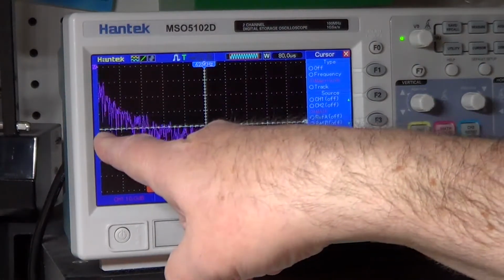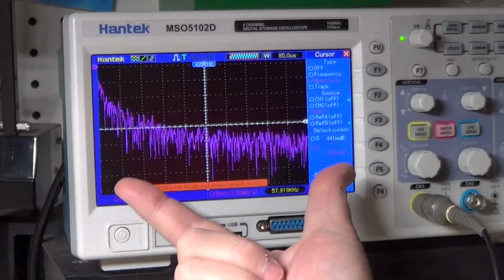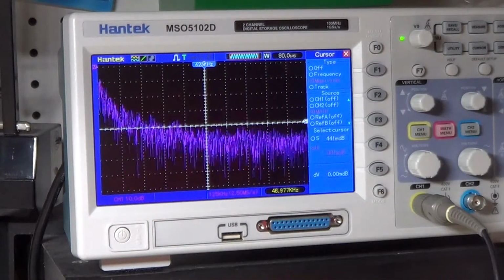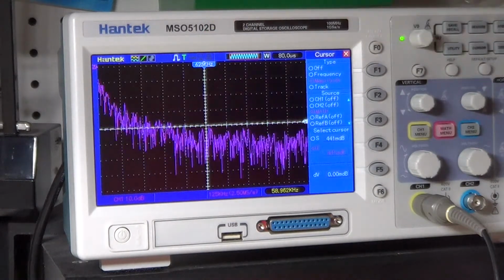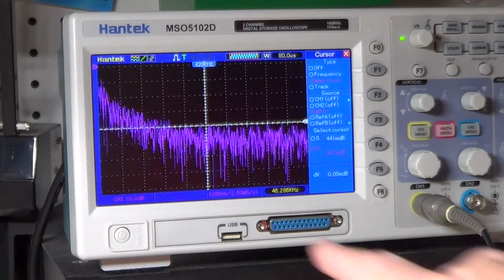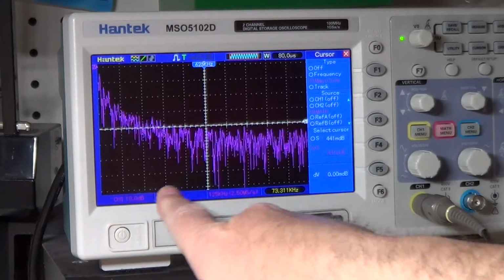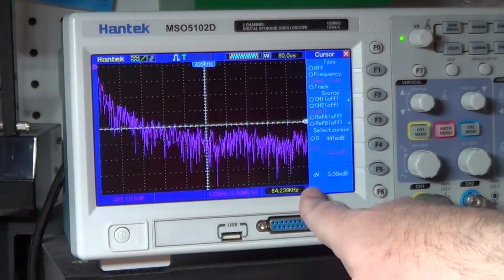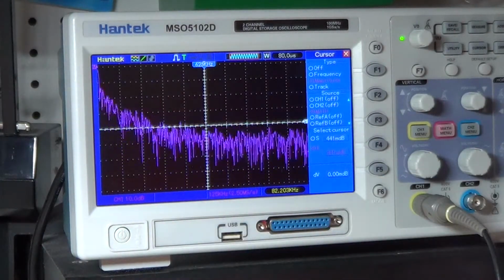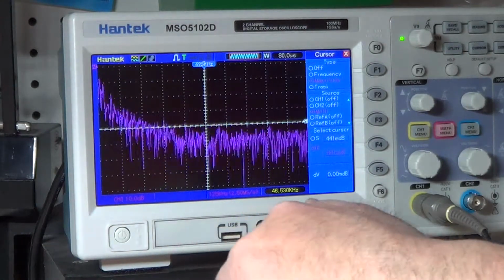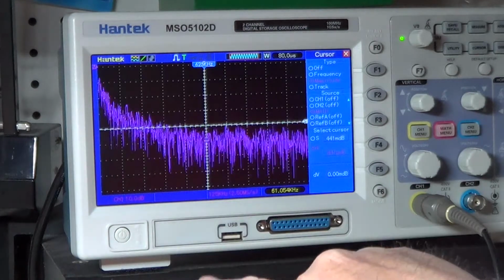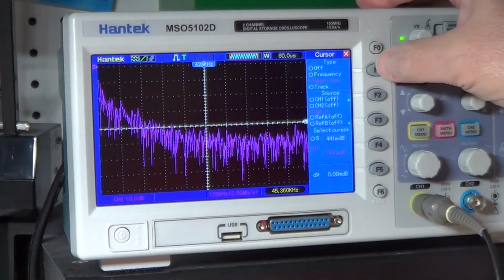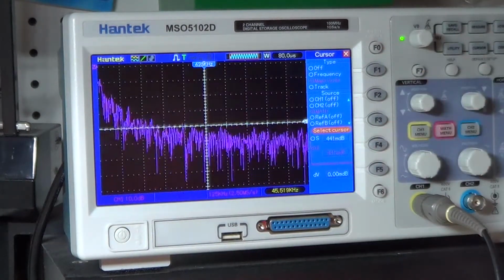Okay, first of all, what we want to do is to identify the interval where we want to make our measurements. Since we are centered at 625 kHz, probably the best thing is to start from here, which is 125 kHz, up to the end, which is 1.25 MHz. So here the frequency is exactly 10 times what is here. So I'm gonna use the magnitude cursors to show you what happened now.